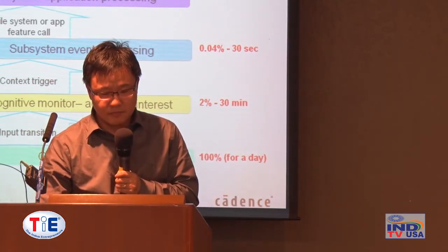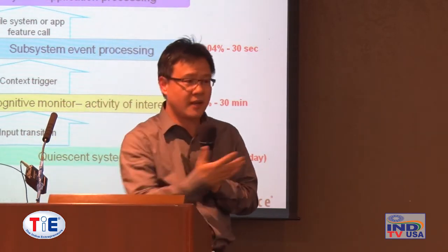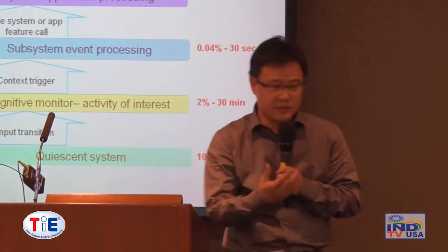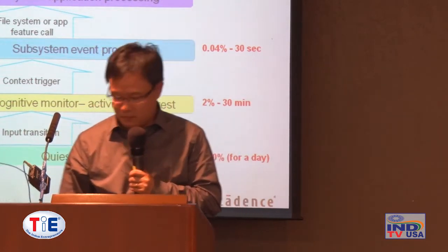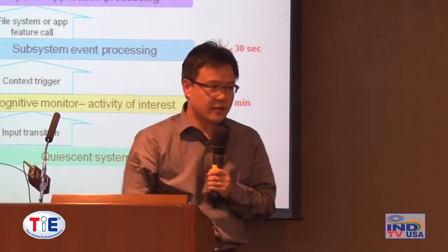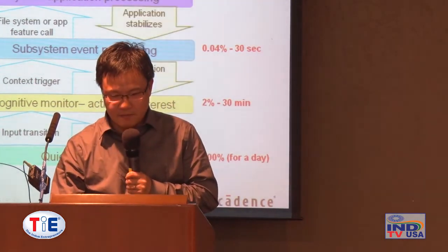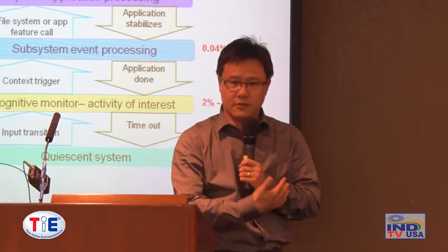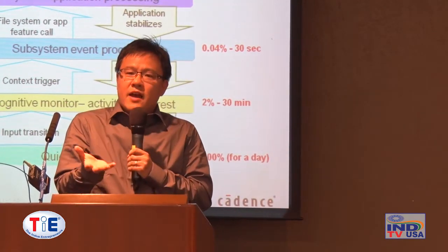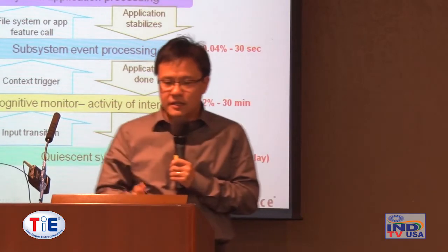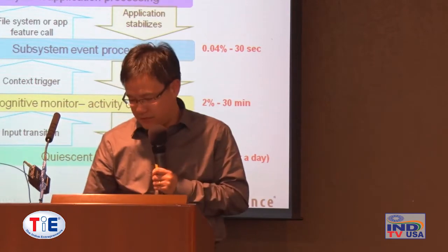And then you move to a subsystem to do event processing. And then you do system level processing, which needs pretty big power, like a typical mobile SoC, which consumes a couple hundred milliwatts to 1,000 milliwatts. And then you have the cloud server that consumes larger than a watt. And that gets fed back to your leaf device, which is a little IoT or wearable that you have. So the key here is that you have to design your SoC or your system in those different cognition layers in order to gain the energy efficiency.